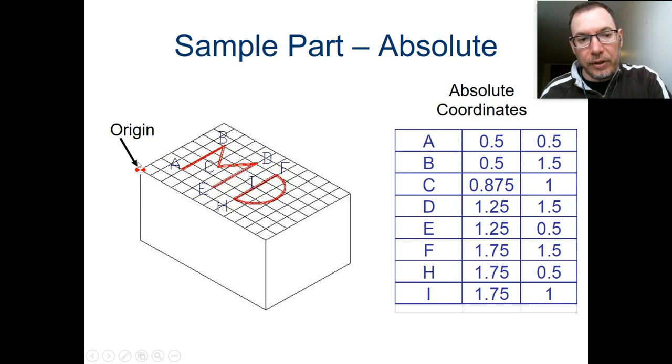And it's the top edge of the part. The reason we pick that top edge is because that is going to be Z zero. Anything above that would be a Z position that's not in the material, and anything below that would be cutting. So anything negative is a cutting height, and anything positive is a height where we're not cutting material.